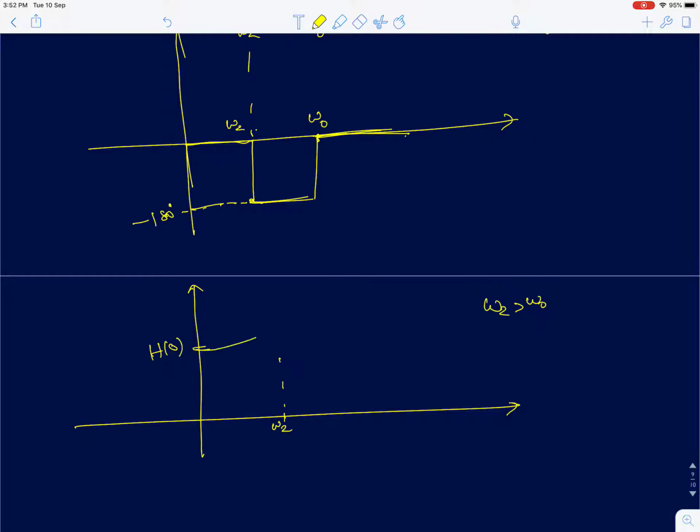So this will look like a low pass transfer function initially. After that, the function would start rolling off, and first you are going to hit omega naught, and then we'll get a 0, and after that the function would reach a constant value in the steady state.